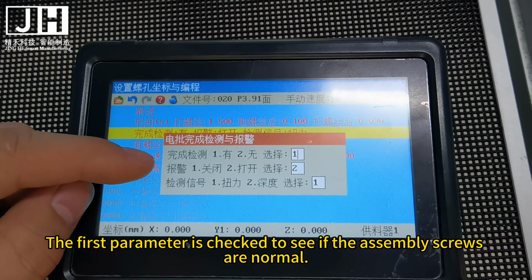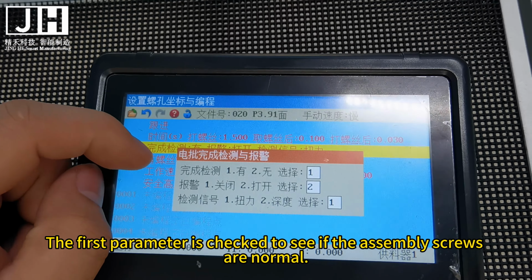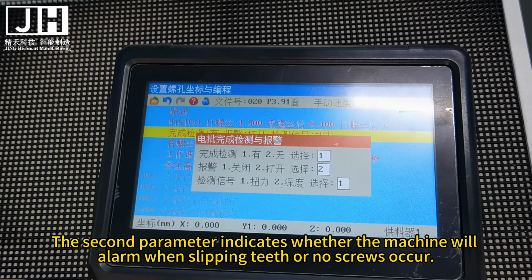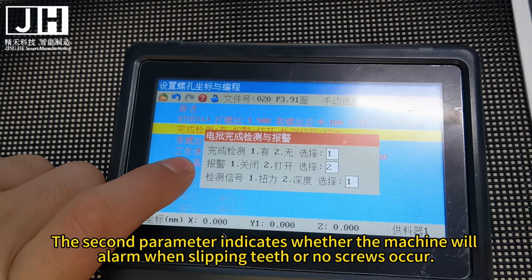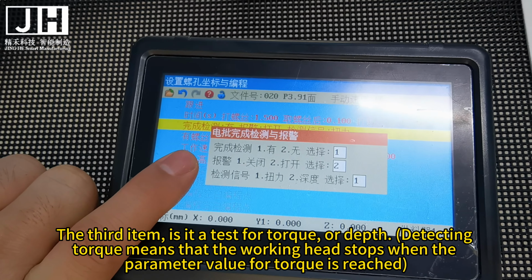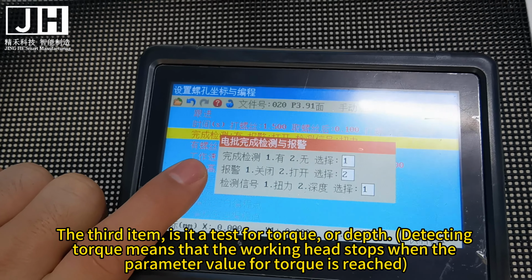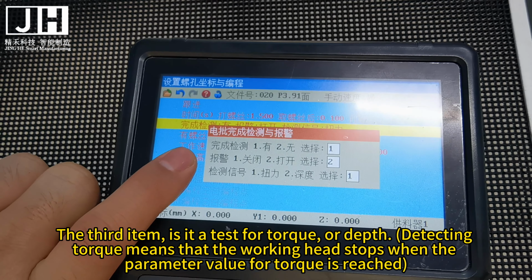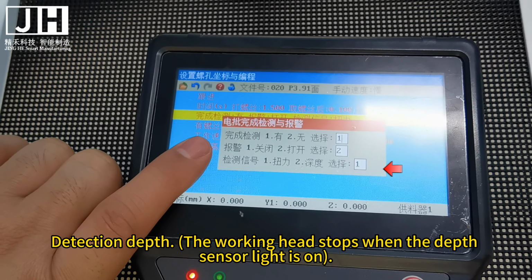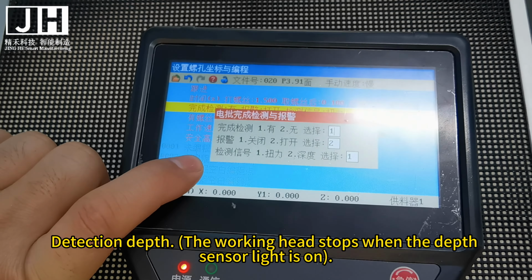The first parameter is checked to see if the assembly screws are normal. The second parameter indicates whether the machine will alarm when slipping teeth or no screws occur. The third item is a test for torque or depth. Detecting torque means that the working head stops when the parameter value for torque is reached. Detection depth, the working head stops when the depth sensor light is on.